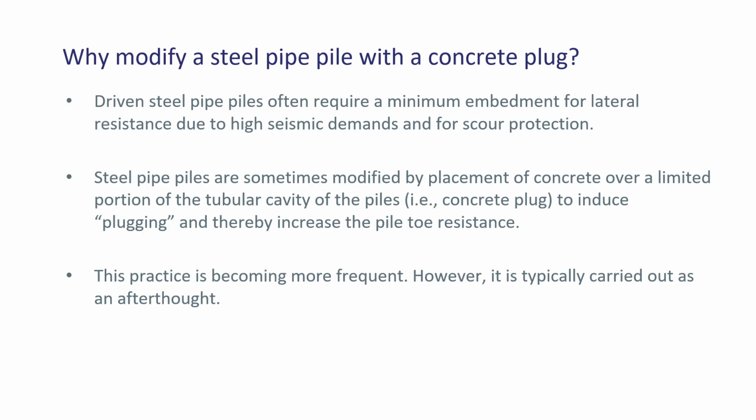Again, last year, Juan Carlos talked a little bit about the challenge we have with pipe piles, especially open-ended pipe piles. They typically core once we get to any kind of reasonable diameter. It's very difficult to fully mobilize toe resistance with a pipe pile in a high-strain dynamic test. We saw that quite clearly with the George Massey Tunnel and the large diameter piles. We get 18 to 20 meganewtons with a high-strain dynamic test, maybe 24 or more with a static test, right? So we're leaving a little bit on the table with the dynamic test.